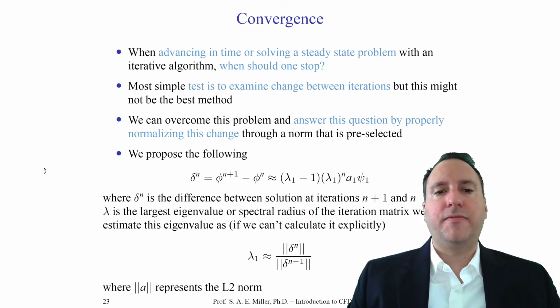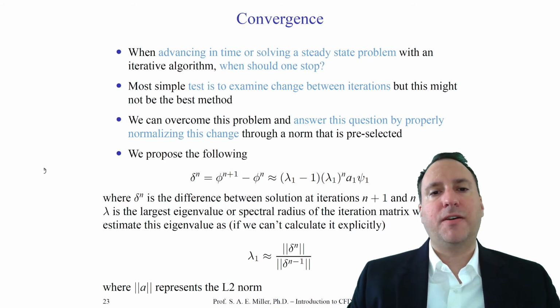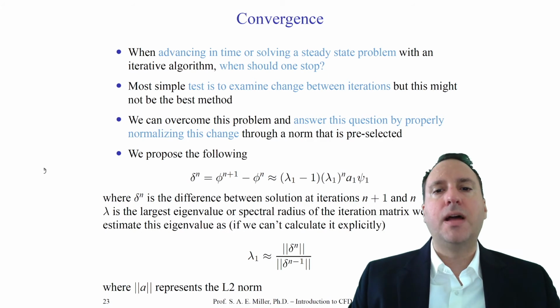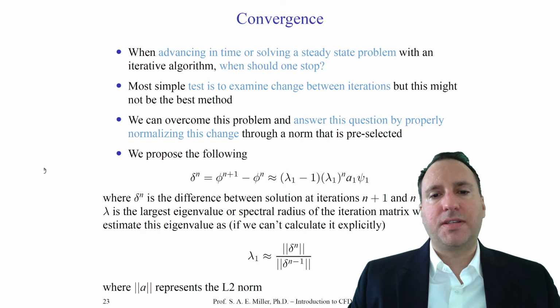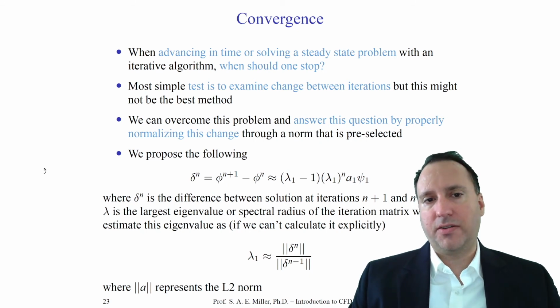For example, if I'm plotting the residual of the equations with iteration for a steady flow, it should eventually become very small and constant, typically 5 to 6 orders of magnitude reduction of the residual is appropriate for a typical steady run. You should then also inspect the solution itself and make sure it makes physical sense. You should also apply a grid-independence study. All these things should be done before you say, I have a converged solution which is physically correct.